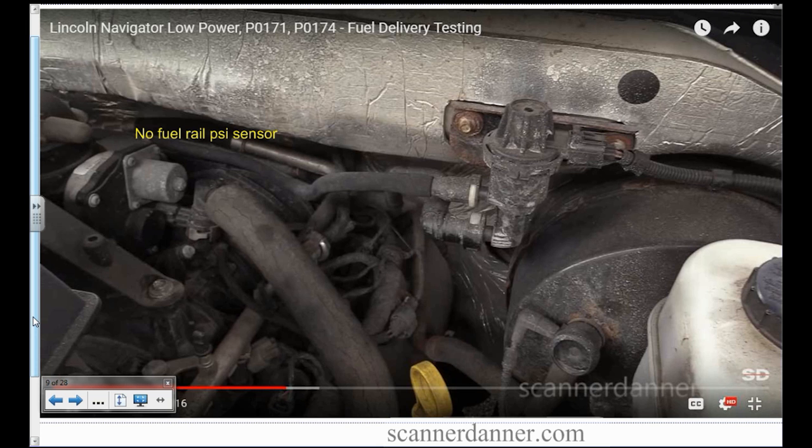Here's the point. There is no fuel pressure sensor on this Ford. I'm concerned with fuel pressure, so I need to know what system I'm dealing with, and this is not an electronic system. Here's the other clue for you guys with electronic systems: there'll be a data PID on the scan tool that says fuel pressure. Not fuel tank pressure. That's for our evap system. It will say fuel pressure or fuel rail pressure. You guys understand the difference? Fuel tank pressure is evap system. Fuel rail pressure would be our injection system. All right.